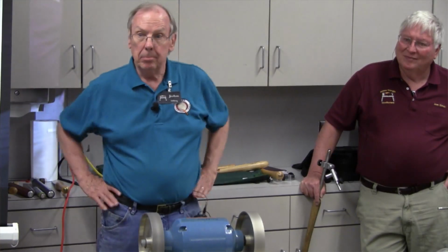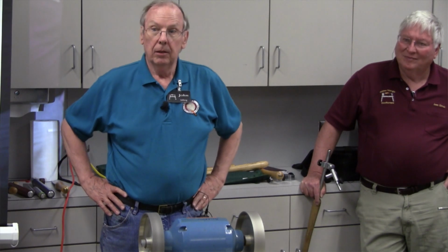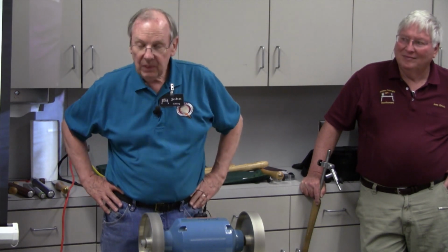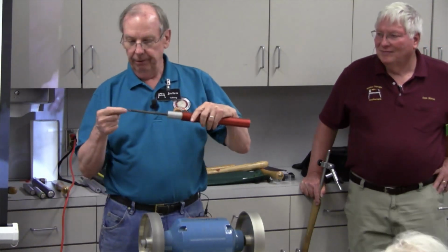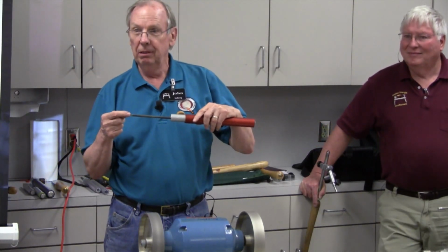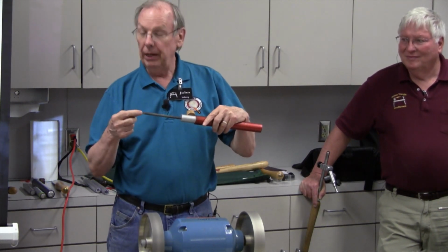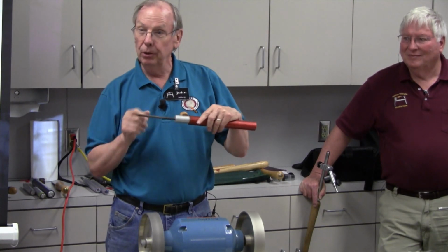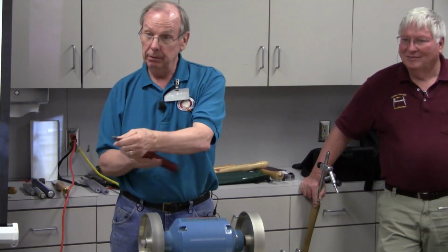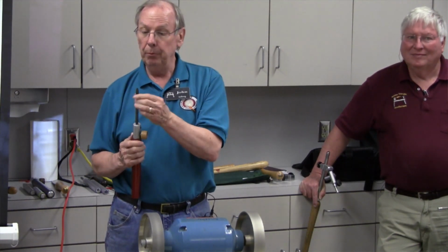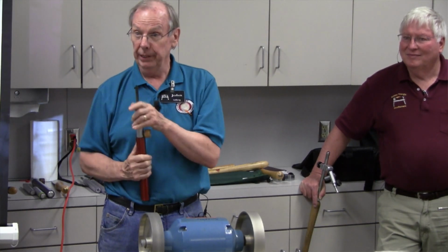You start with the sides, both sides, and sweep it in to the ends. I start with the sides because I consider the tip the expensive part of the tool. The sides are cheap. So I grind the sides first, but I don't want to be shortening the tool. Then once I get the sides ground, I blend everything and make sure that I don't get a really sharp point on the tool while I'm sharpening it.